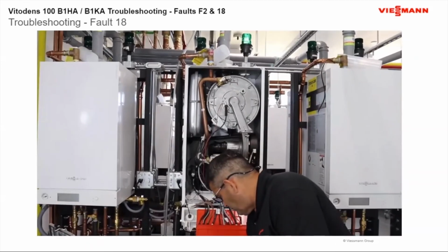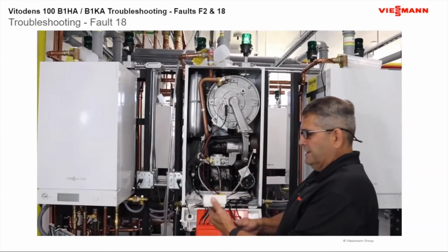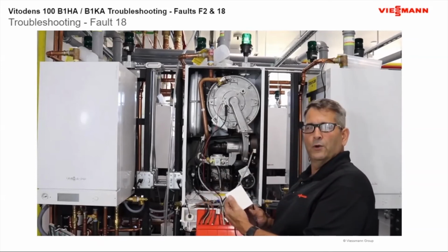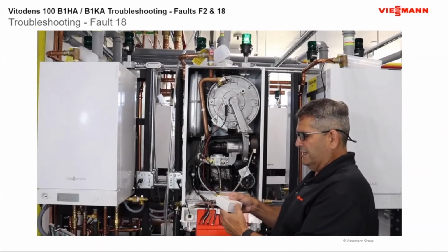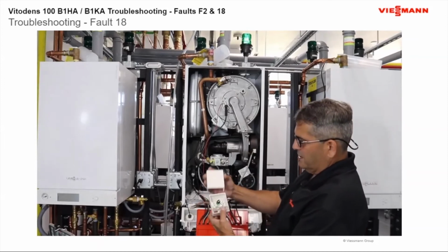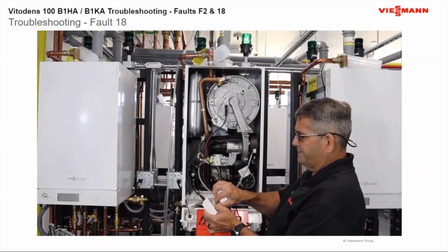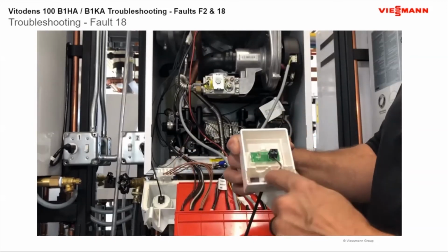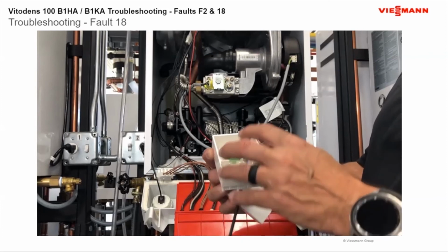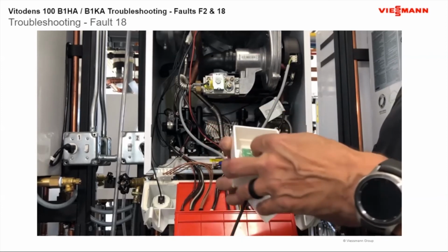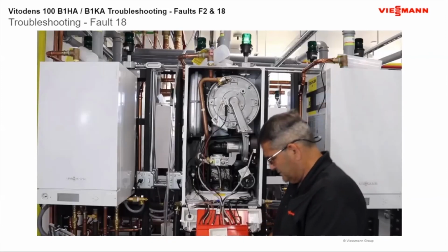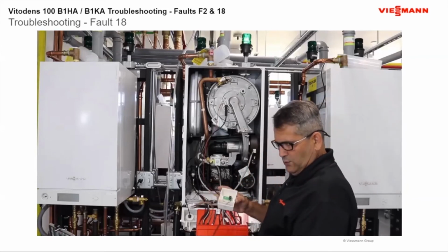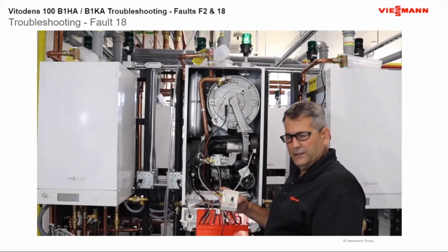Let's say we're not getting a reading going out. That could be a wire, so what we're going to do is go outside, take the cover off our sensor itself, take the two wires off, and then do a continuity check on our wires. So we're going to take these two wires off, twist the two wires together, and then go back and check your wire. And we're going to keep it on continuity.